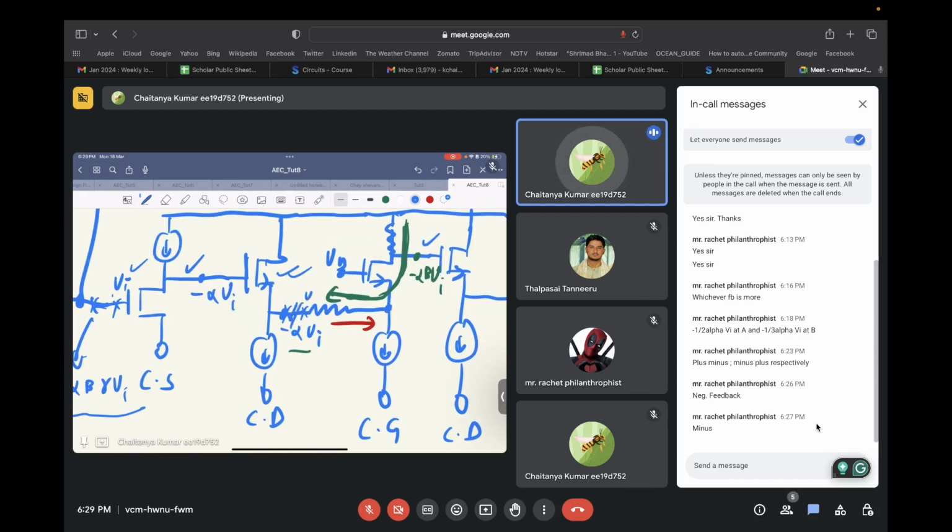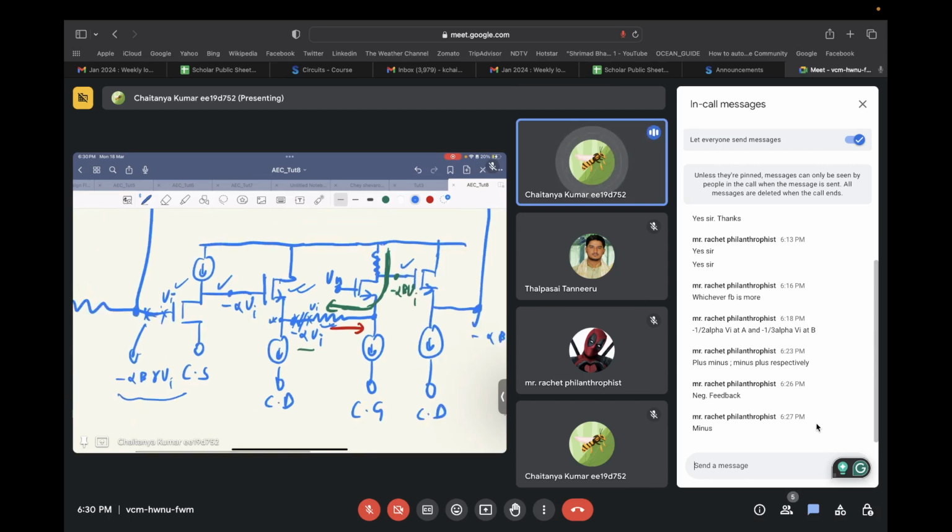You will apply an input voltage over here. Then through the complete loop, you will get some output over here. In actual practice, this particular resistor was loading this node. But now, since this resistor is not loading this node, you will get a value that is higher than what actually would have been. So you should be careful. If you didn't want that, then while breaking the loop over here, you should have put a resistance of the same value at this node.